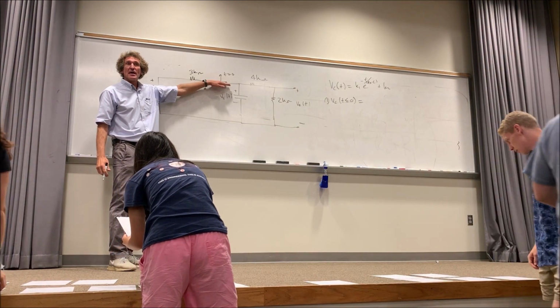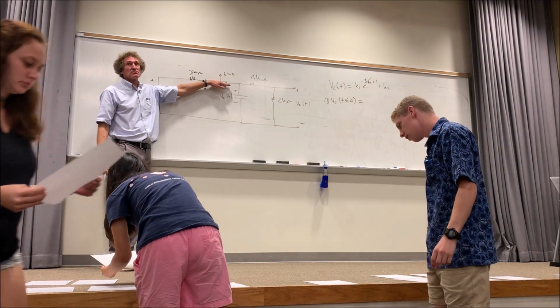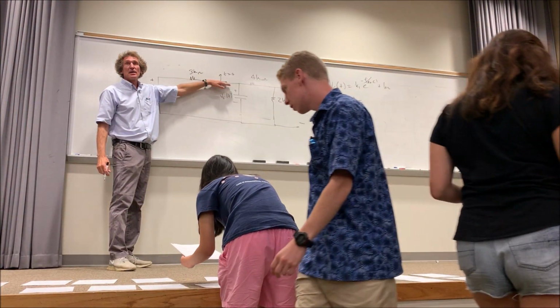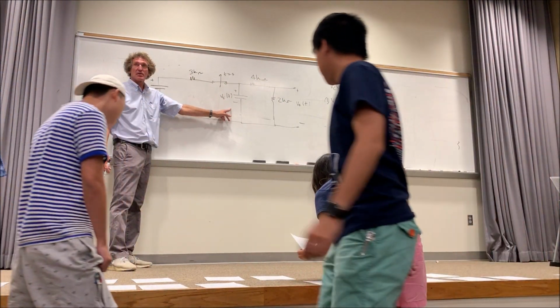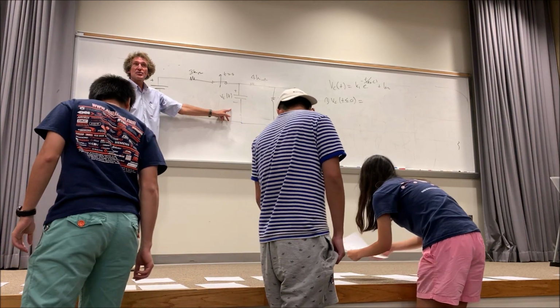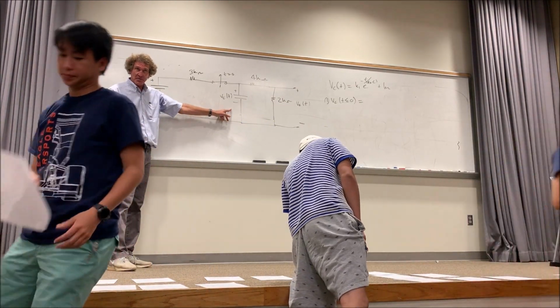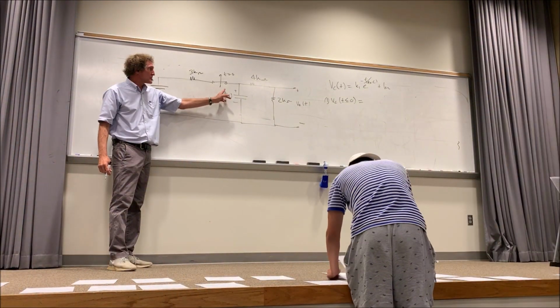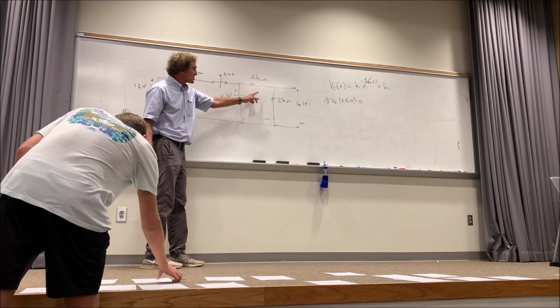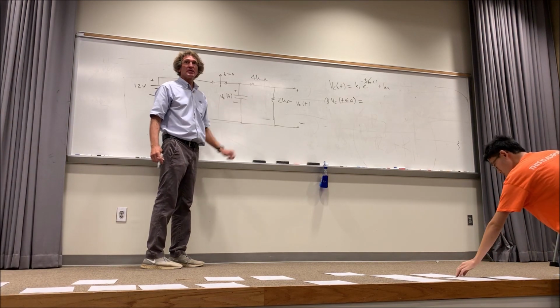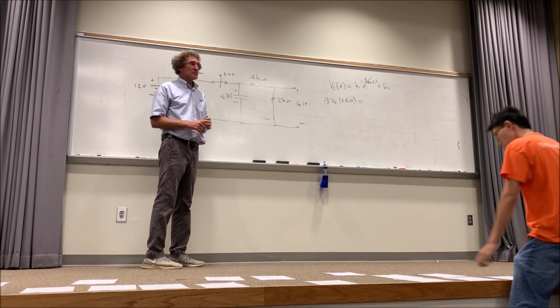You'll follow me on that. It has been closed since time began. What does the capacitor look like in that domain? T less than 0. Class? Open circuit, because there's nothing changing. You follow me? So the voltage across this capacitor is really the voltage across these 2 resistors. Does everybody see that?